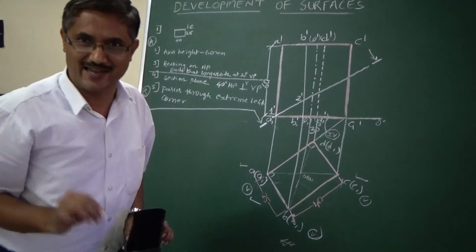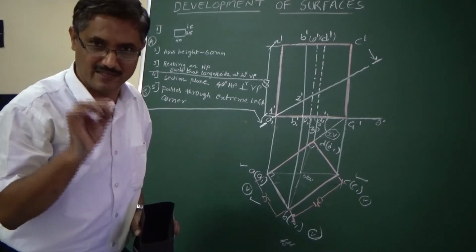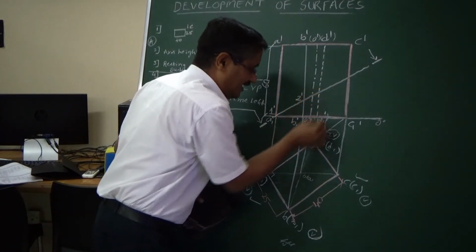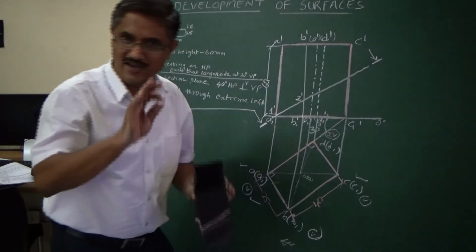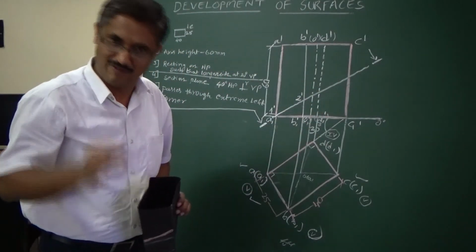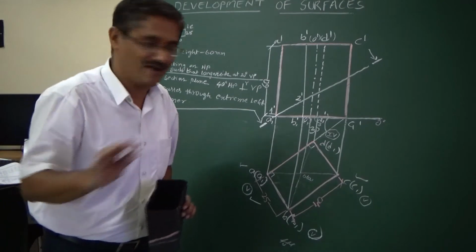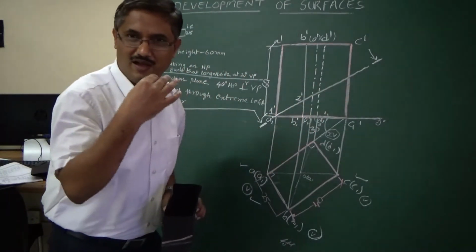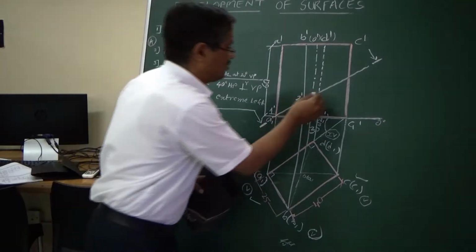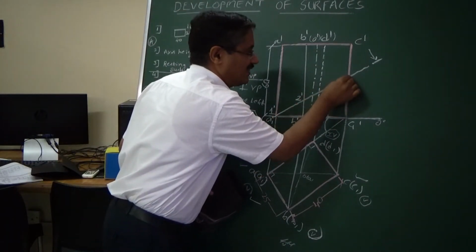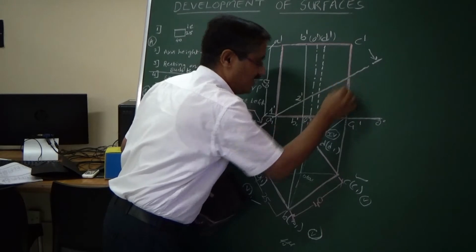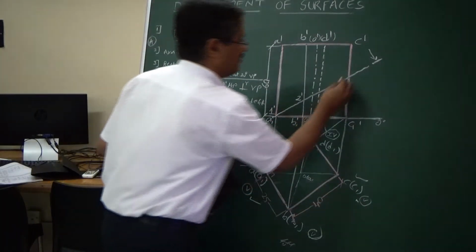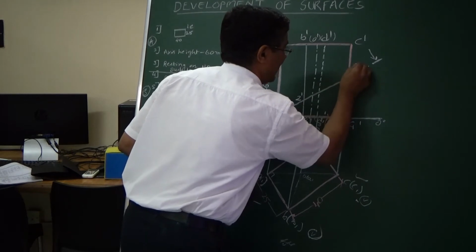Don't number that axis line, you need not number it. Just move ahead. Again you get DD1, which is dotted. Don't number it immediately. We have to number the dotted line, but not now. We will move further to check the visible longer edges. When you move further, you get one more, CC1, which is visible according to the problem, so you number this as 3 dash.